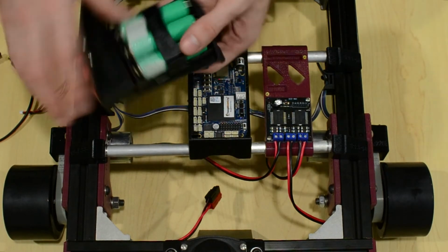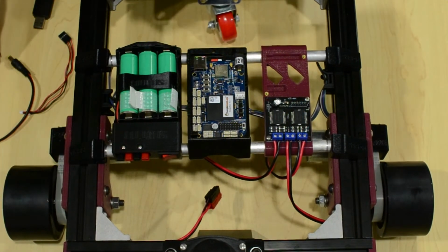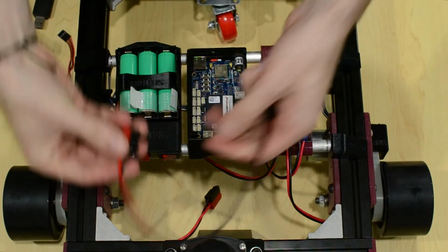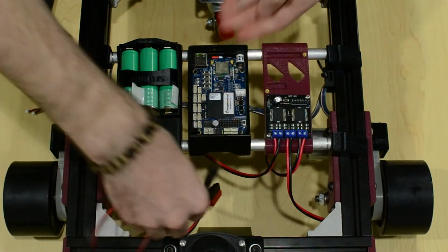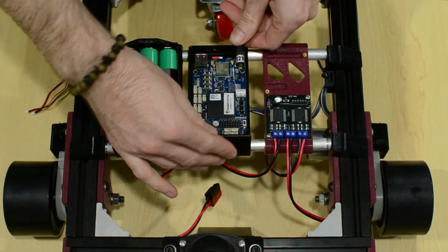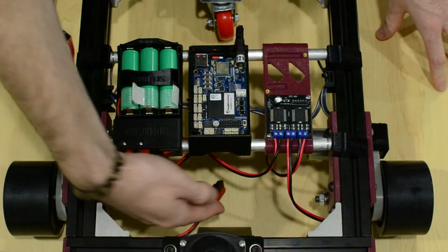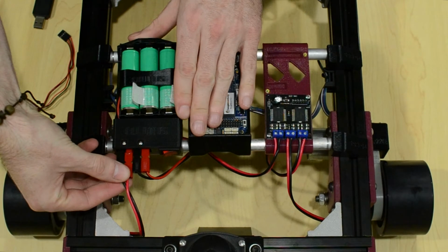The first step is to place the battery like this. Make sure that all your batteries are in the correct orientation. Then connect the BeagleBone Blue using the male barrel plug to Anderson connector, and then you can connect the cable that's going directly to the driver. In the case of the video, my driver power cable goes through the frame. That's why you cannot see it.